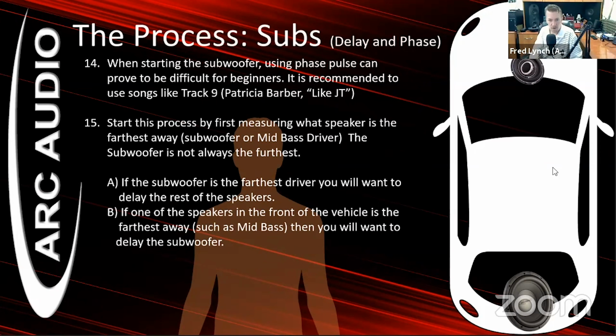If the subwoofer is the farthest away and you're hearing the information and you can't correct it that way, then group all your mids and highs together and increase the delay there. Just remember, whatever speaker is farthest ultimately ends up reigning supreme here in setting delay and phase. So just to recap, if the subwoofer is farthest away, increase the delay on your mids, highs, and tweets. Check phase, acoustical phase, by flipping it 180 degrees in the software first on the sub before you do this. But if, say, your mid-bass driver or your mid-range on your passenger side is farther away than what the sub is, then do everything with the sub itself versus the mid, high, and tweet.